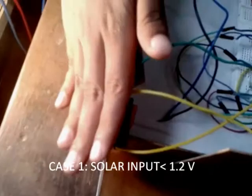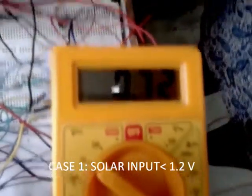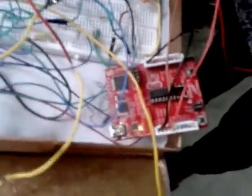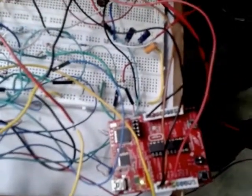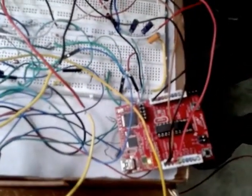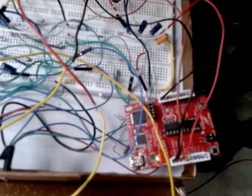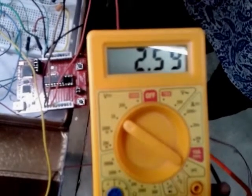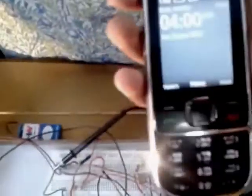Let us consider the first case. We are going to block the solar input. The input is only 0.71 volts. As the boost converter cannot function with such a value, the microcontroller instructs the switch to open so that the boost does not receive an input and the phone does not charge. 2.5 for the switch means the switch is open and the phone is not charging.